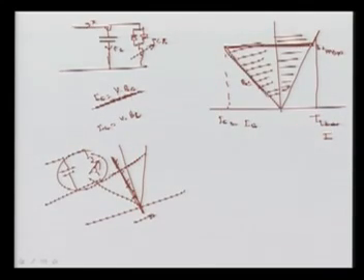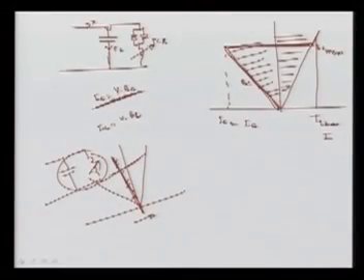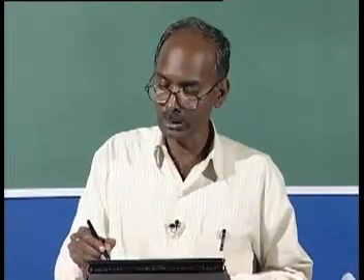We operate normally in the capacitive zone. When the voltage is less, we must operate in the capacitive zone, because we require reactive power and we must supply it. So our characteristic here normally moves here and then slightly going here, and then to this point. It means that when the voltage is less than the reference value, we have to operate in this zone because we have to provide this. If voltage is more, then we have to go this way.